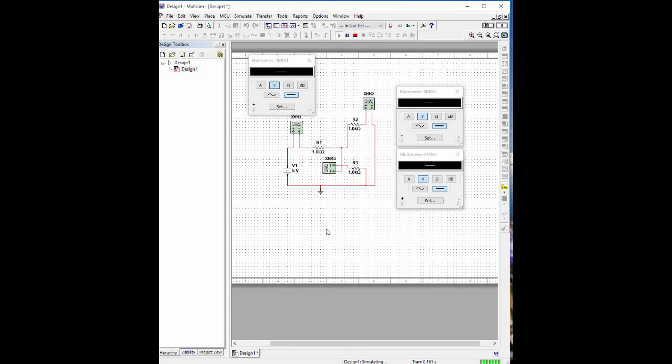You understand the point. Actually, it is good to see the point. Now if we run this simulation, we see that the input current which is going into the node is 3. Oh, sorry, those are voltages. Okay, so we are measuring currents, so I'll just change things to currents. Okay, so the input current that goes into the node is 3.33 milliamps. The current that leaves here is 1.667 milliamps. The current that goes here is 1.66 milliamps. If we add these two up, they should give us this one.